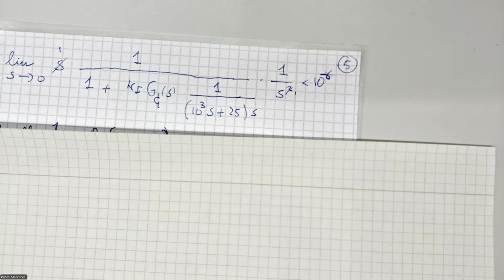The auto parking in the Volkswagen is realized with an adaptive P controller. We don't have an integral because the integrative action is in the system itself, if the goal is to achieve the position.